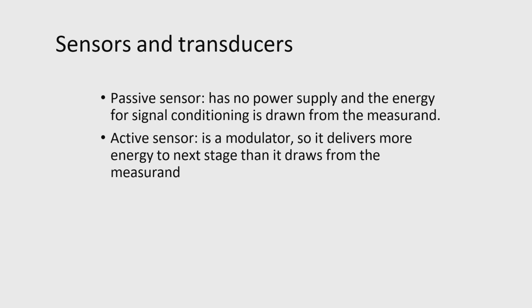Therefore, many times people get confused about sensors and transducers. In fact, in many books you may get different types of definitions. So, here I explain in my opinion that a transducer is something which transforms one form of energy into another form of energy. Suppose you have taken displacement, and displacement motion has been transformed into an electrical signal. Similarly, you have a pressure transducer in which pressure has been transformed into an electrical signal. So, pressure is a mechanical energy and you got electrical energy.